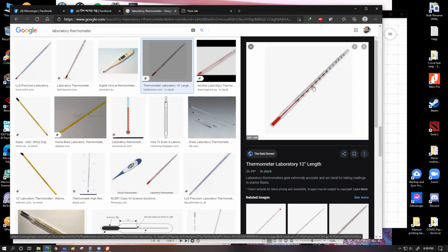What I wanted to understand: let's say this is an alcohol thermometer. Pure alcohol is a colorless liquid, and a colorless liquid would not be visible within glass equipment. So we actually add some coloring agent within the alcohol. We choose that coloring agent with proper consideration, and also add a certain amount within the alcohol, so that the property of alcohol to have uniform temperature behavior, the linearity property of the alcohol, is not destroyed.